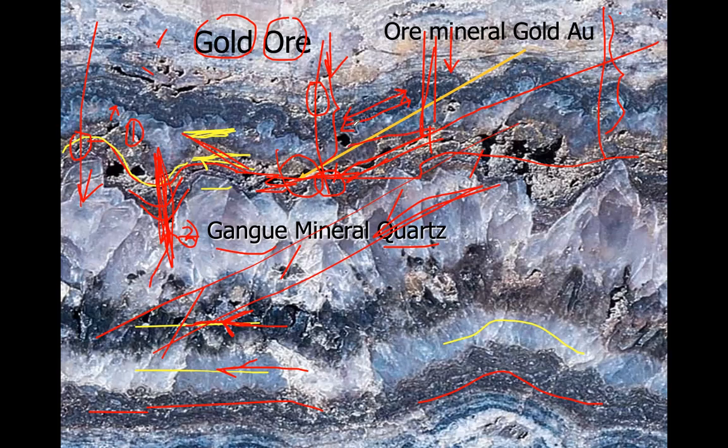So therefore, this angle is very important. Such a stereographic projection method can be used to find exactly the more appropriate direction to drill, right? So structural geologists know that, and also economic geologists who are involved in this mineral exploration know how to apply those stereographic projection methods to find out the drilling directions.